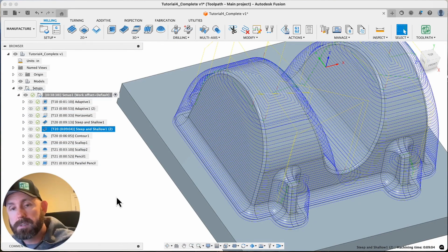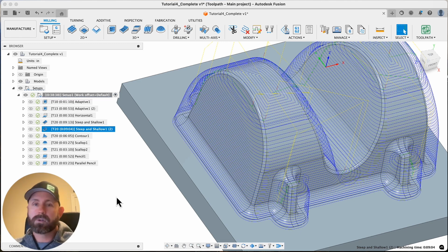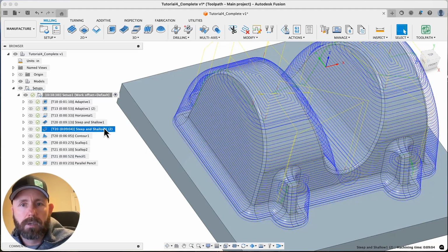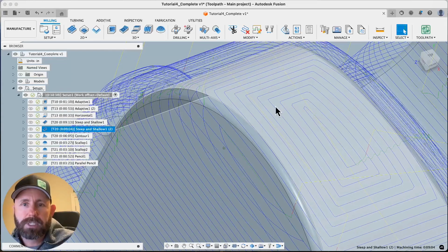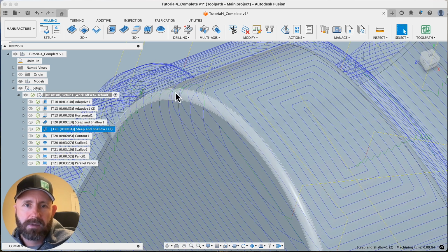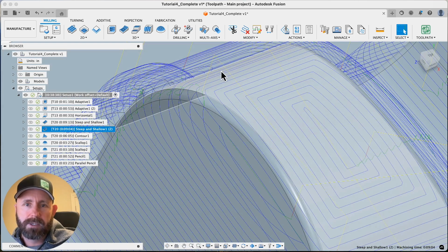It's great because it works at basically all the surfaces. It's what I would call a surface step over toolpath. It steps over evenly on the surface no matter the inclination of the surface or the angle of the surface. Okay, so we could make this better. My machine, and every machine made, doesn't like to go haul butt down this direction, make a hard turn that direction, just like a race car on a racetrack. I wouldn't mind this nice curved corner over here, but it definitely wouldn't love to make this U-turn here. And the smoother we can make those, the better.